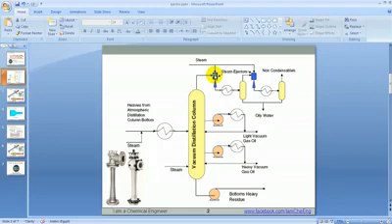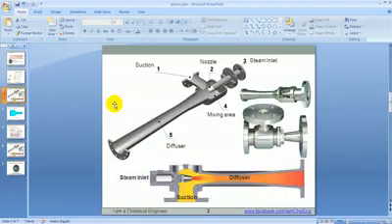A jet ejector in more detail consists of two nozzles. The first nozzle is for the first fluid that applies vacuum, which is usually steam, and is named a wet jet ejector. There are typically two types of jet ejectors: wet jet ejector and dry jet ejector. A wet jet ejector uses steam as an input, as an applier for vacuum. The dry steam jet ejector uses air as the main fluid.